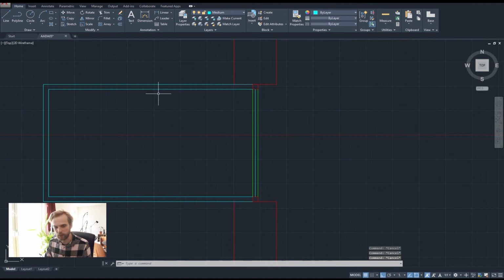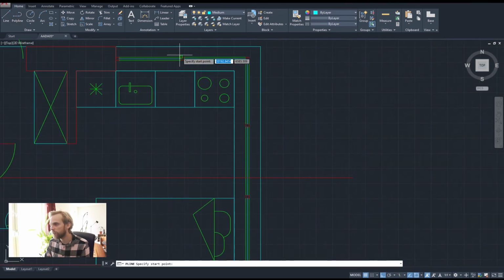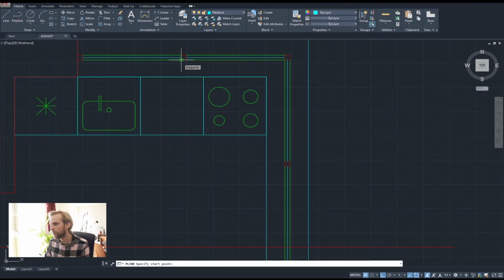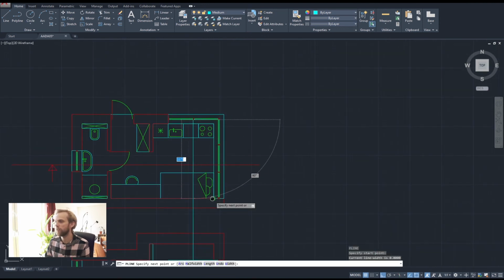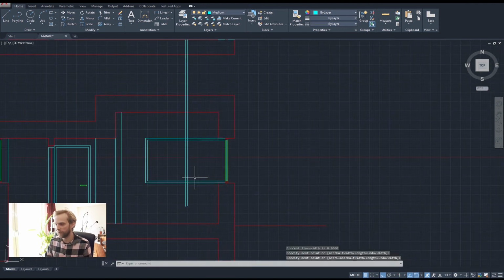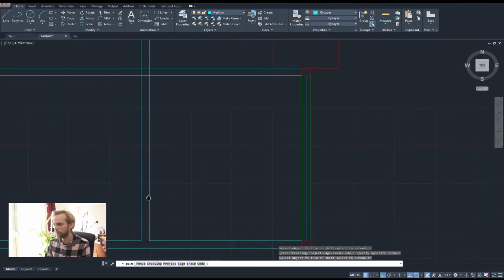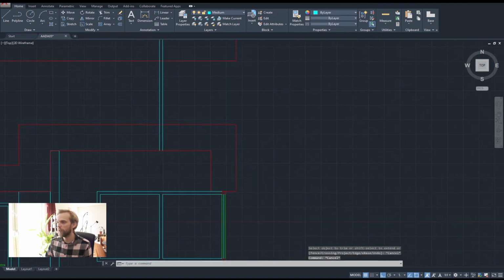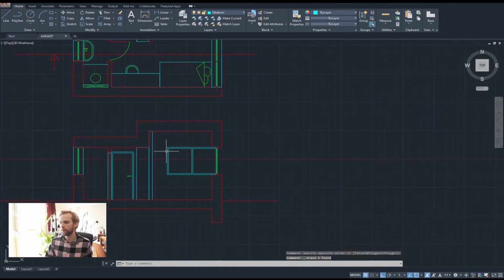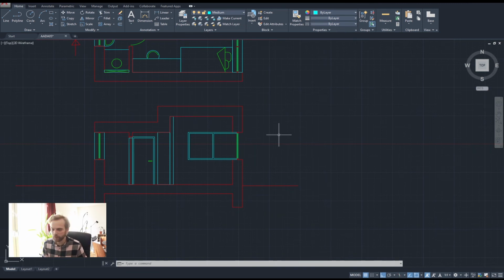So this is the frame that we see, right? Now I can see that there are going to be divisions here. Well, at least one division here. So I'm just going to kind of draw out those 2 lines because I'm lazy. Like that. And I'll use trim, enter, enter, to kind of clean everything up. So, come on. There we go. And then get rid of the rest. So that's my window. That's all I need to show.